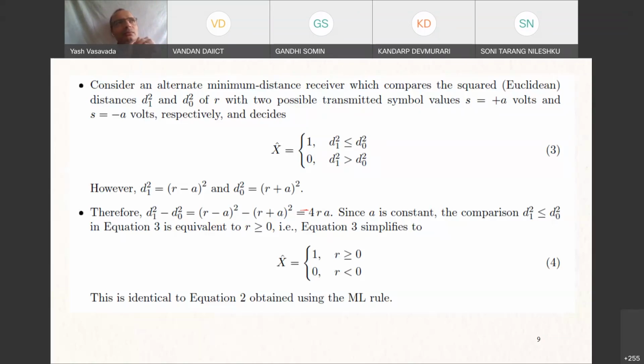Why are we minimizing the distance becomes the question. Typically, minimization of the distance is considered a good thing to do. The trick is in defining the distance. For modulation, the distance is very easily defined as Euclidean distance because we are dealing with numbers on the real number line. For channel coding, we were not dealing with actual real valued numbers, and so we had to define the concept of distance more carefully. And that is where we came up with this Hamming distance concept.